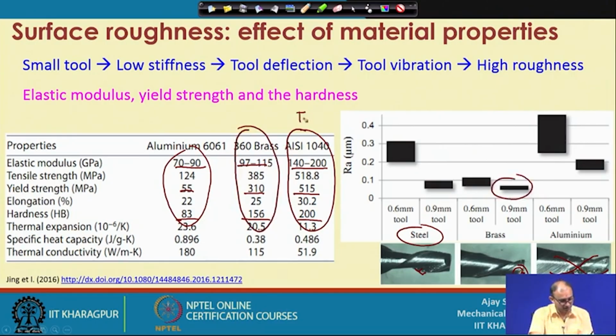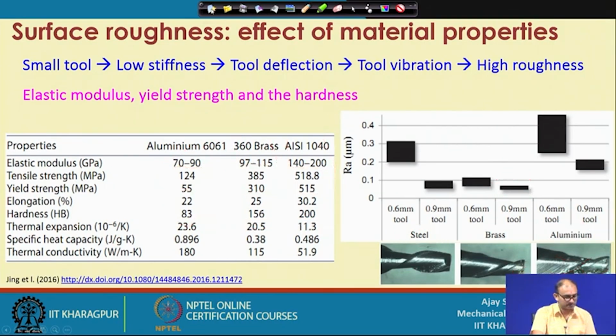So, here the tool wear is a problem, and here the material removal is a problem, correct. So, this way, because anyhow you have to cut the aluminum, but you have to finalize the process parameters in such a way that you do not end up with this. You use some type of mist coolant and you add some type of projector with a high pressure, so that it will remove these things very easily, right.